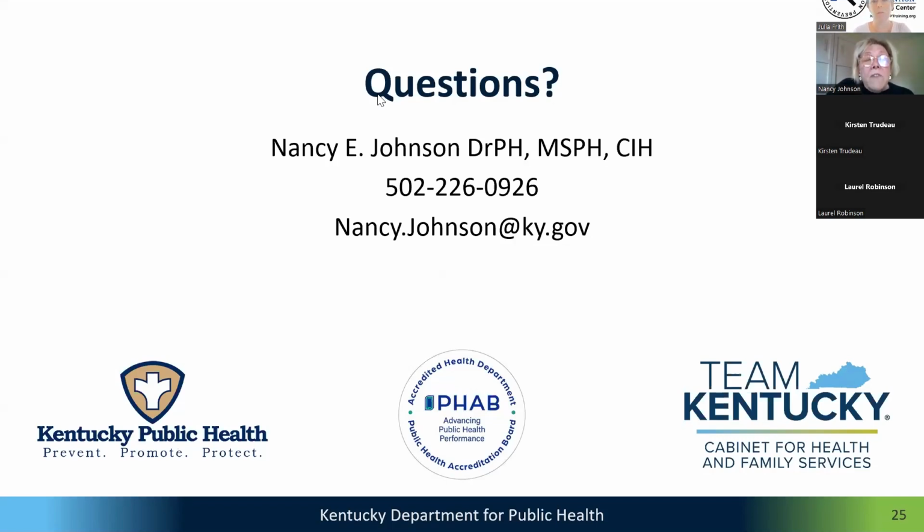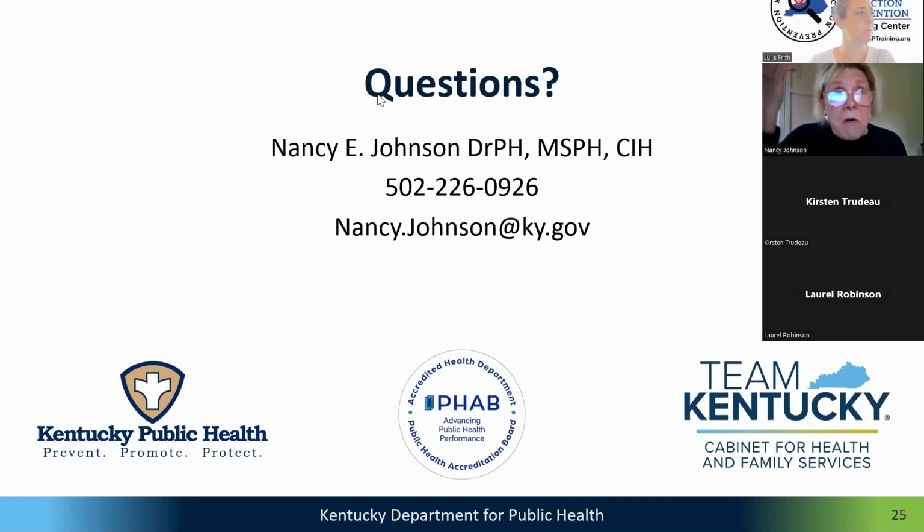If you are looking for dead legs, you should look everywhere in your building. It sounds silly, but it's a hidey hole for microorganisms. It's a place that's quiet. The water still communicates with the rest of the water system. And we've had situations where they just cannot get it out of a certain fixture.